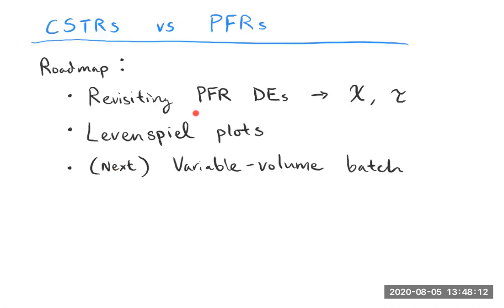So let's go ahead and focus on PFRs here. I'm going to go back and remind us from our generalized balance, we were able to derive from first principles equation 3-26. And that was for PFR. So we have dVr. Oh, and there's actually nothing on the denominator here, at least as written this way. It's dVr equals d molar flow rate of I over Ri. This is our PFR design equation.